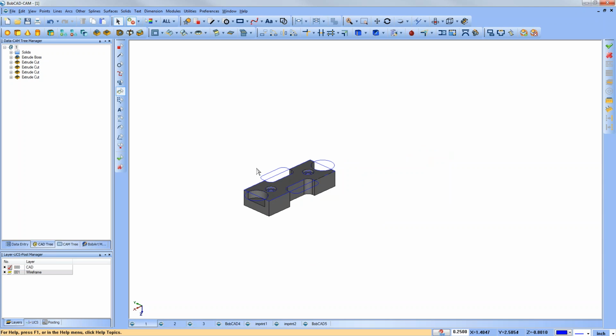If you had a cylinder and wanted to cut holes pointing to the center of that cylinder, you can draw an extrude cut, or before you extrude cut, do a revolve around that shape and then do extrude cuts individually in towards the center, and you could set the depth. That's one way you could handle that. I'm not sure if that's what you mean. Otherwise, you'd have to create the geometry and maybe do a Boolean subtract.